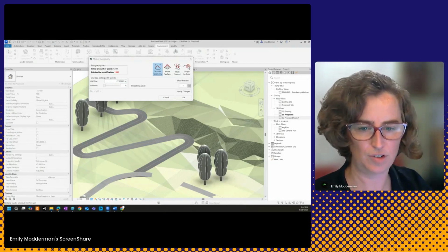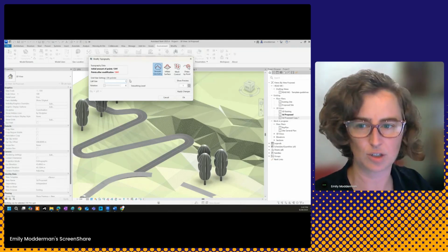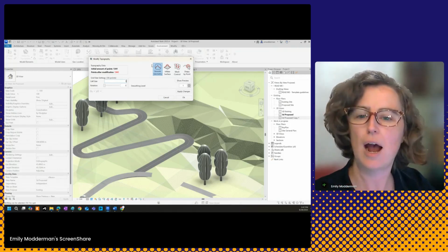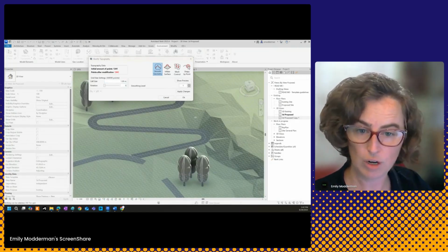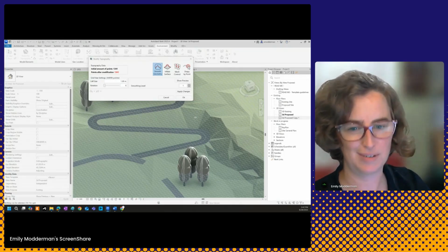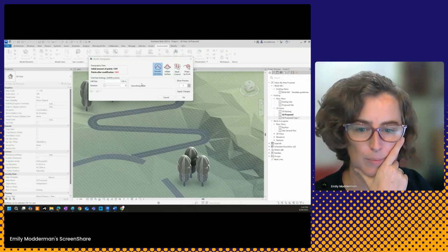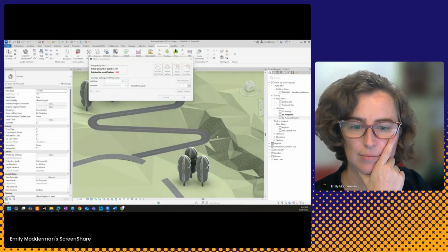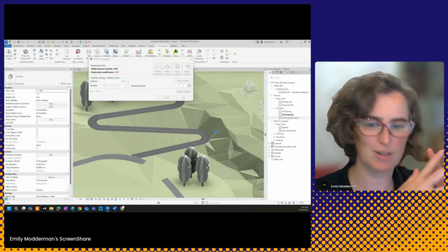All right, so I'm going to smooth some of this geometry off, and we'll see what it does. First of all, I'm going to set my cell size to something a little smaller. Now, I hope this doesn't crash right as my exit strategy, but I'm going to set it to 1 meter of a cell size, because if I leave it huge, the smoothing that it's going to do is going to ruin everything that I've worked on. So I can set that cell size to something more reasonable, and let's see what we get. I can show preview. It's going to analyze this for a second. It's got a lot of modifications to do, so fingers crossed this doesn't take me too long.